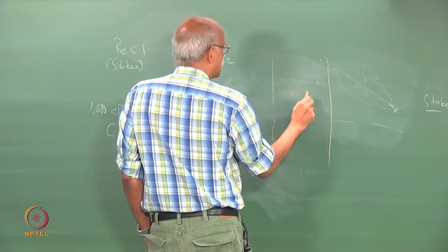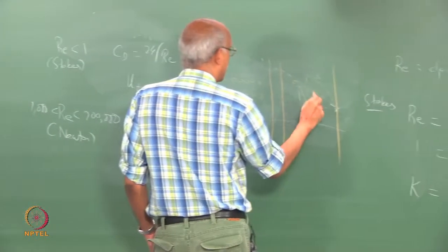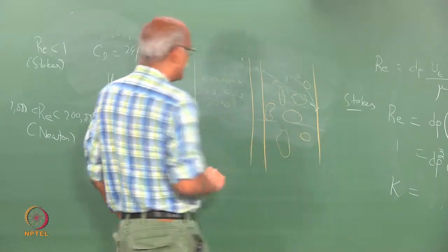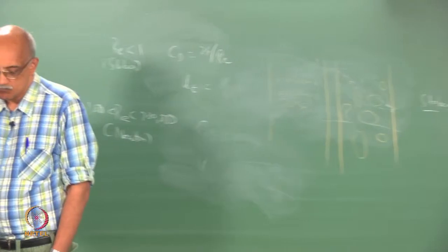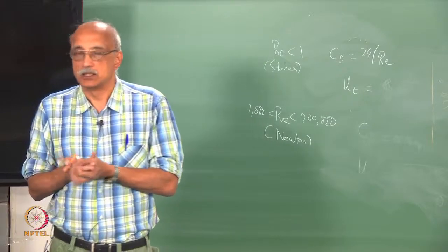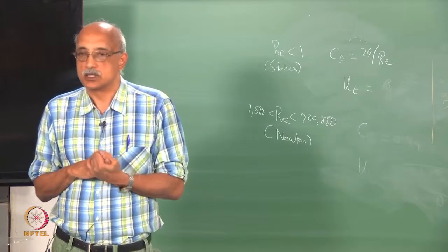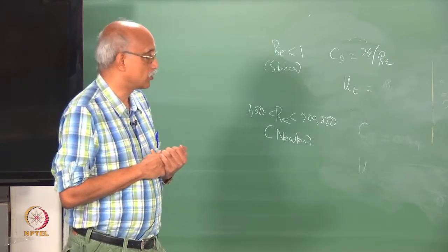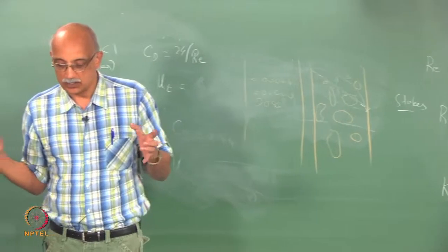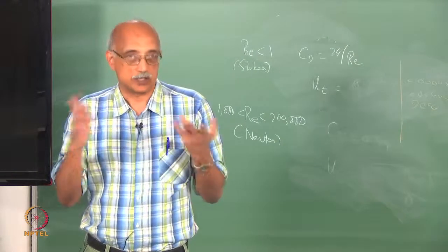So in the case of spherical particles, so if you have a packed bed and you have, let's say, 100% spherical particles versus a packed bed where you have a mixture of different shaped particles and so on, which do you think, let's say for the same mass of material that you have packed into the bed, which do you think will allow more pathways for motion of the fluid? Is it the one where you have all spherical particles, or is it the one where you have a variety of shapes? In other words, which configuration is more accommodating, where the particles can slide against each other and minimize the void fraction?